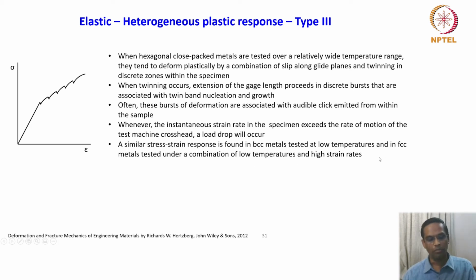So what we have to appreciate here is that whenever you have a constrained deformation, either in the form of low temperature, high strain rate, or the lack of slip systems, something like that, wherever you have a constrained plastic deformation, this kind of phenomenon can occur.